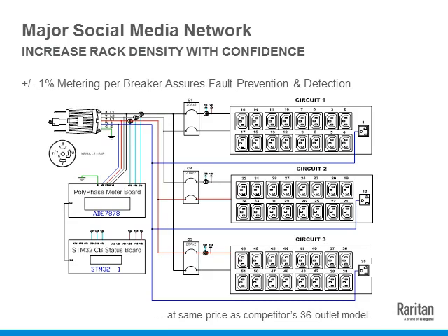So in those scenarios, what we had to do was to manage every single circuit very carefully. So the circuit breakers, in this particular case, there are 3 breakers that are protecting each of these branch circuits. Each of those breakers are monitored closely, and the accuracy on those is plus or minus 1%. So how does that matter? Let's say if the accuracy is plus or minus 5%, that means you can leave 5% of the capacity that's available to you on the table, because you don't know for sure if you have that or not.